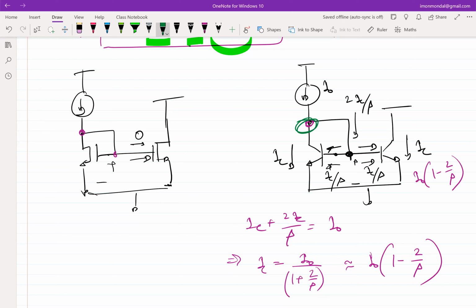Okay, good question. But since we have learned everything in terms of VCCS, we will also follow VCCS. That is one of the best practices, because ultimately we want to control current. We want to apply some voltage at the input, and so on, right? So it makes sense to treat it as a voltage controlled current source. But having said that, if you look into the literature, you will find that it has been treated as a current controlled current source also.